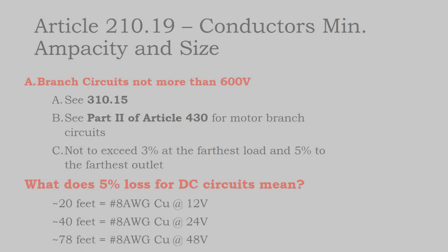It doesn't have anything to do with whether it's DC or AC, although finding equipment might be hard if you're running oddball DC circuits. It's really more to do with the low voltage of a 48-volt battery bank. We want to step that voltage up so that we can push it further. Your 120-volt circuits and your AC service panel can push electricity a lot further than a lower voltage DC circuit.